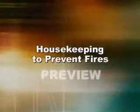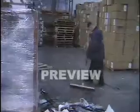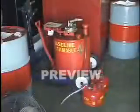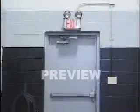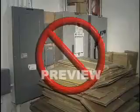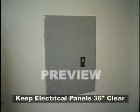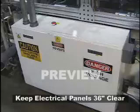Housekeeping to prevent fires. Good housekeeping ties in closely with fire prevention. If you allow debris or flammable material to accumulate, the risk of starting a fire increases. Keep equipment and materials in their proper locations, and make sure all exits, hallways, and corridors are kept clear. Not only is it a bad safe work practice, but it's also a serious safety violation to block any emergency exits or electrical panels. In fact, fire codes require that they have 36 inches of clearance.